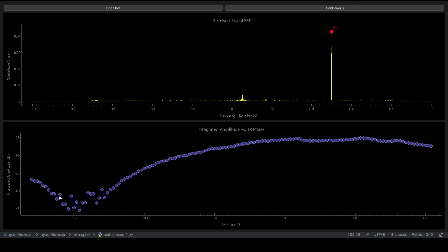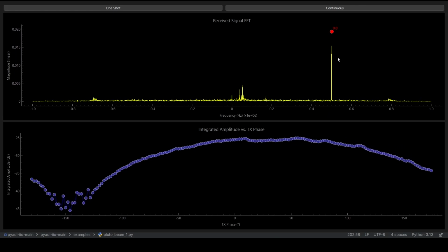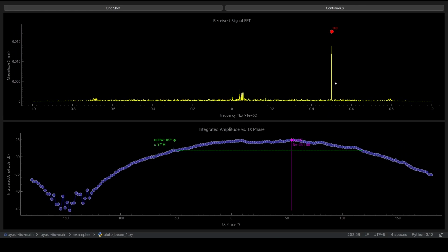One interesting thing was that in the initial phase, where the amplitude of the signal was low, these non-ideal, low frequency tones at the FFT had power comparable to the baseband tones, so we were seeing them on a larger scale.